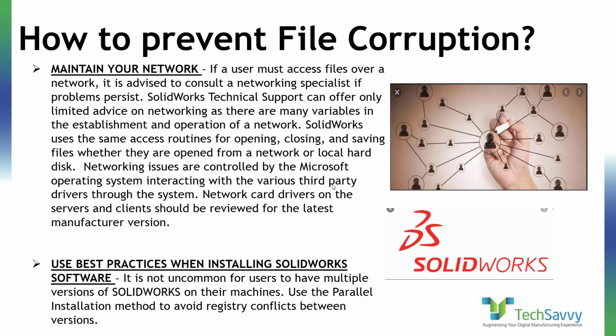Last but not least, use best practices when installing SolidWorks software. Whenever you are installing any SolidWorks software, don't use multiple versions of SolidWorks on your system. Use the version in which you are working, because parallel installations should also be avoided to prevent conflicts between versions.